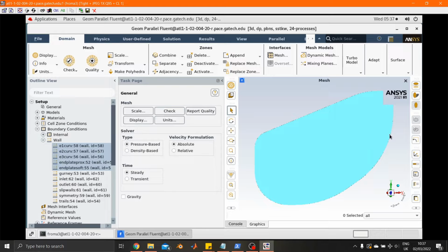It looks okay. But if we hit the ruler icon right here, this icon, we'll see that our rear wing is actually about 1 kilometer long. And that's because there's a funky quirk in Fluent where it reads whatever mesh you made, it reads it in meters, whereas we made it in millimeters. So there's a very easy fix, but just always make sure you check this length right here, because we do not want 1 kilometer long rear wing.